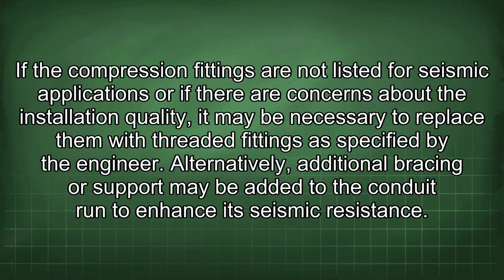If the compression fittings are not listed for seismic applications, or if there are concerns about the installation quality, it may be necessary to replace them with threaded fittings as specified by the engineer. Alternatively, additional bracing or support may be added to the conduit run to enhance its seismic resistance.